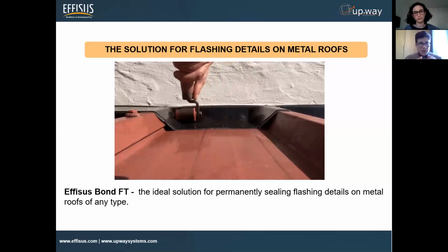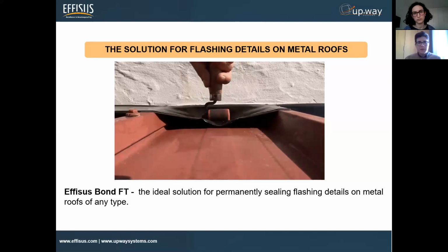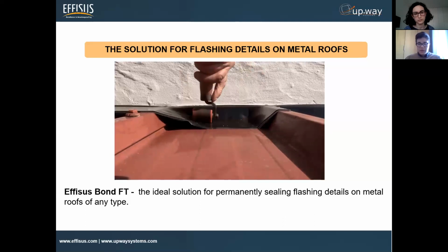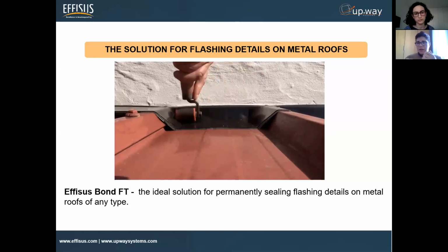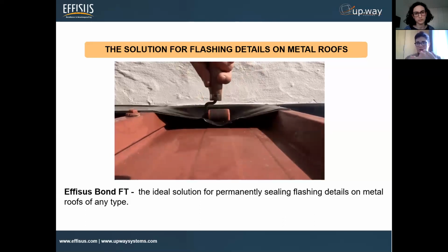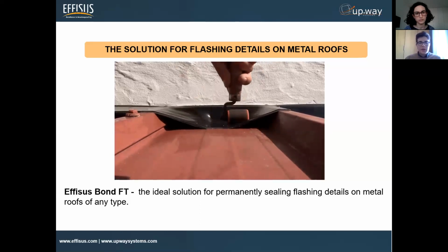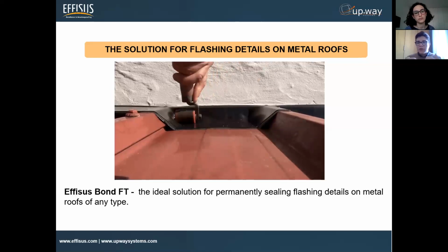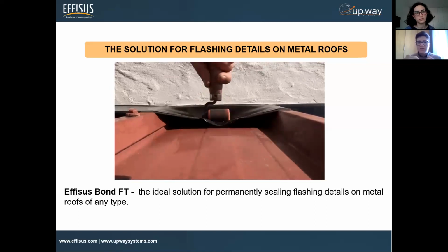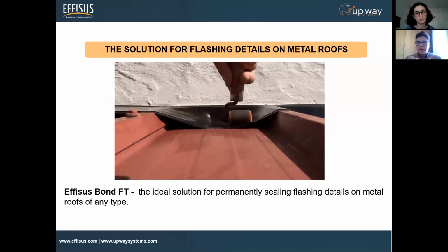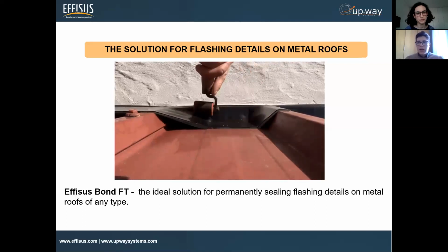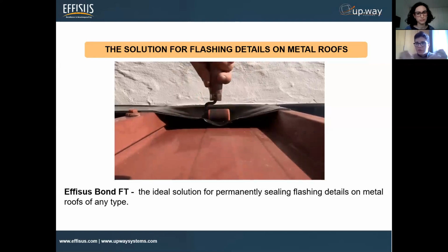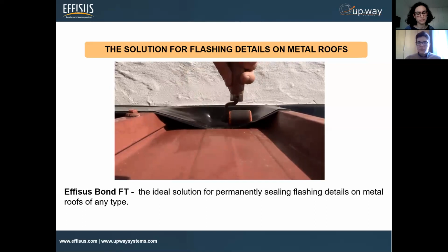Just to go a little bit into the technical aspect. A normal EPDM, a rubber EPDM membrane as we know it, gains the capacity of memory or stressability during the process of fabrication with the changes of temperature. So it's cold and hot, cold and hot, cold and hot. These different temperatures applied during the process of fabrication allow the EPDM membrane to have an extensibility of over 400, over 500%, as we all know.